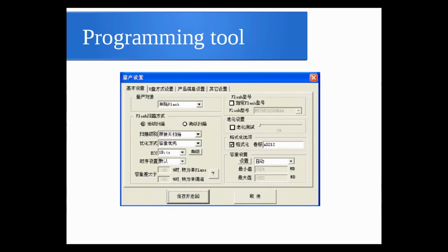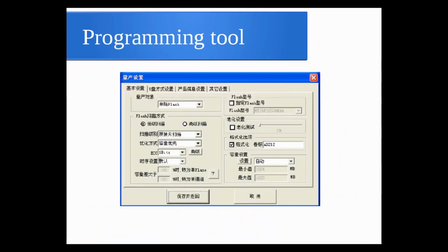So you open the programming tool, it runs on Windows, and you're greeted with this. If you actually translate this, there are some really interesting strings. You can figure out that this is setting every parameter for the SD card that you want to burn. You can set the manufacturer code, you can set the serial number. In the bottom right there, right now it's set for auto, but you can manually specify what it reports the card size to be. Which, if you're making counterfeit cards, is a great box to have.